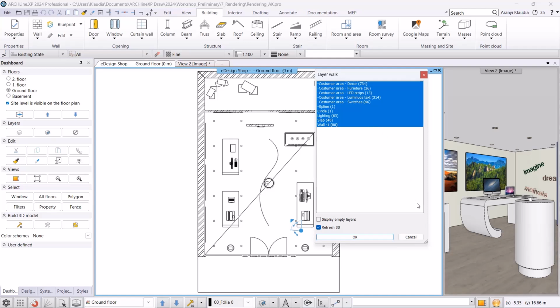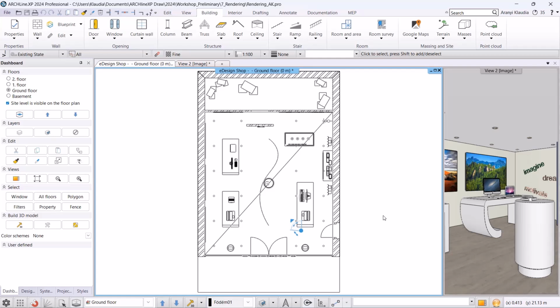A good photorealistic image is not created with just one click. We need to learn how to handle lights and shadows. We need to understand the physical properties of materials, find the ideal viewpoint, and set up the sun accordingly. We need to build the image step by step, and in these steps, we need to continuously create test renders. Generally, to achieve the final render, we need to create approximately 25 to 30 test renders.